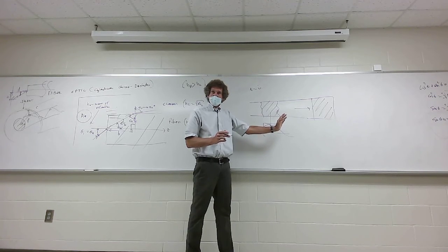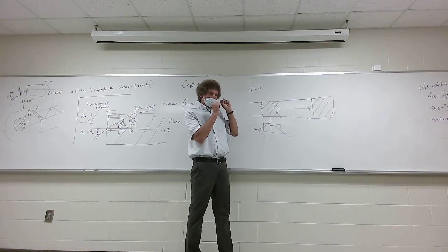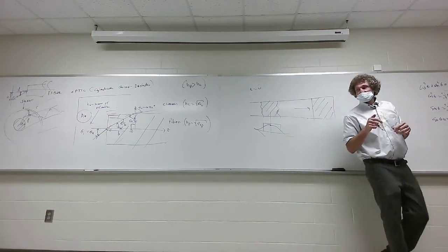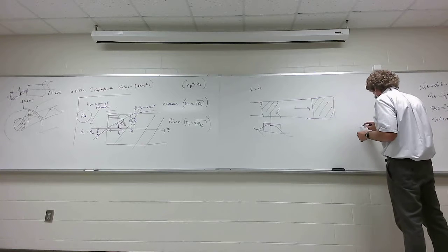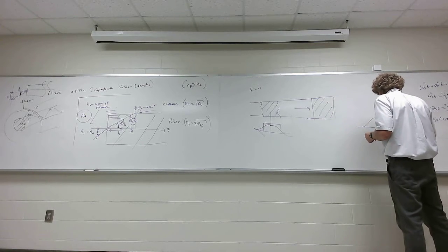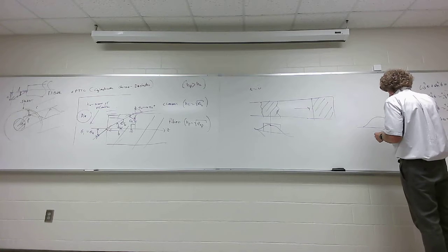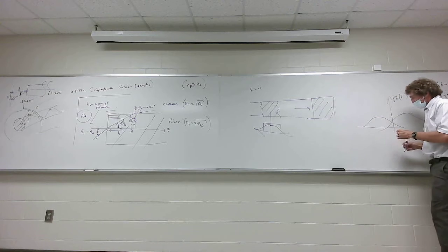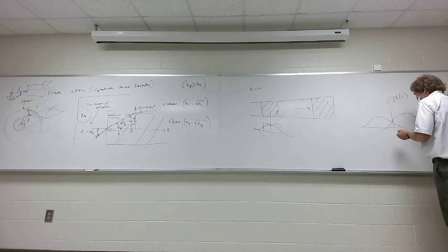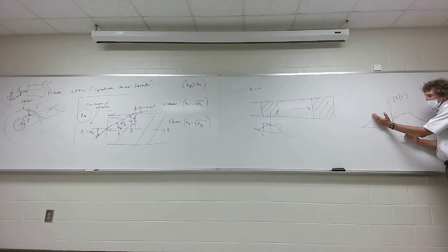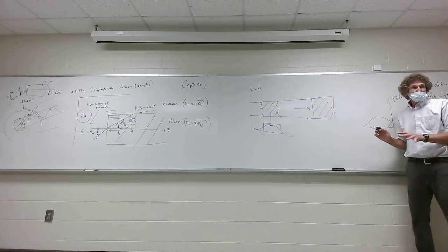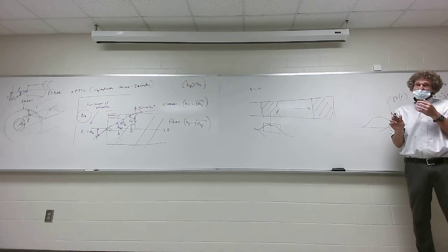Y'all follow me? So that means with fiber optic, because you're sending bursts of light, right? Send a whole bunch of light, then no light. Whole bunch of light, then no light. There comes a maximum distance that you can send this before this stuff starts looking like this, in terms of the densities. If this was the probability density function for photons of a given frequency, and this was the spatial dimension z, then they start to blur together and you can't distinguish where one began and one ended. Y'all follow me? Now we don't get into that, but you have to understand, that's caused by dispersion.